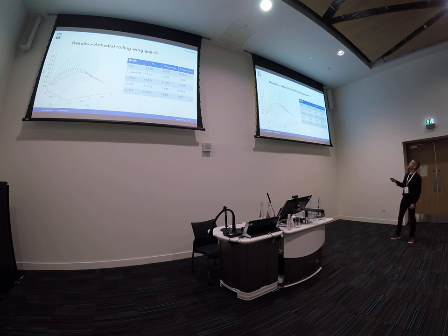And here, what we see is that these results are completely ridiculous in terms of what you usually see. Oswald efficiency for the ideal elliptic wing is 1. Now we have something that is way, way better. And that's of course because now we are making a maneuver, so actually we're putting energy into the system. And that's why the drag can go also below 0.